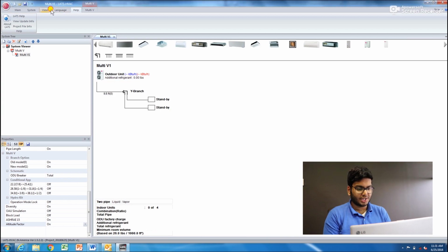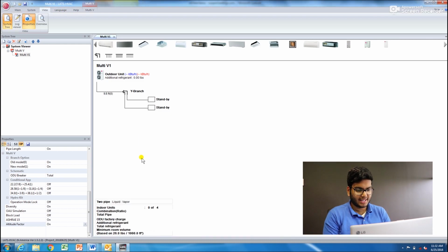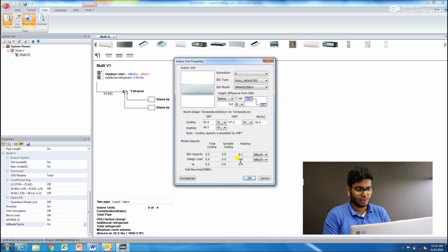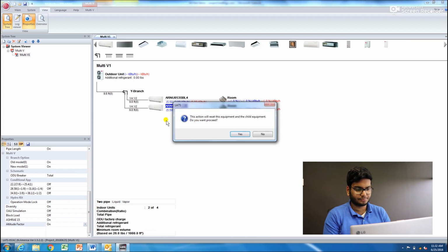The Log Viewer window shows you your most recent actions. The Project window and Overview window are key elements in creating and developing your project. While the Overview window gives you a bird's eye view of the project, the Project window is the initial window where you start a new project off. By dragging and dropping a variety of models and pipe accessories from the box to the top, you can put your project together the way you see fit. A simple right click will give you more advanced options for each specific component, such as deleting or copying.